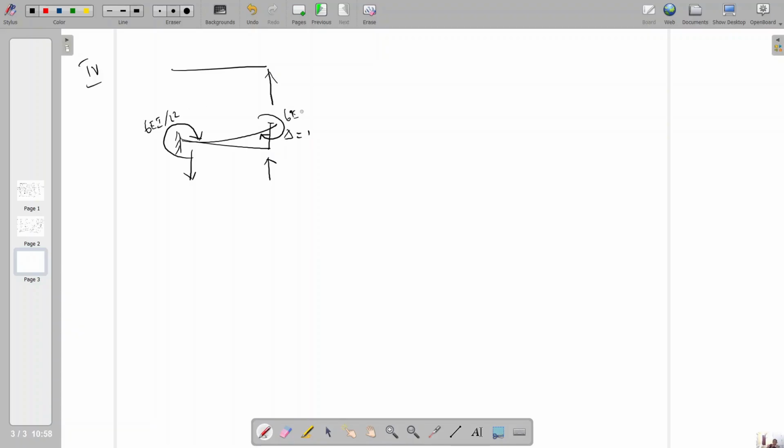So we already know that the moment due to the support sinking is 6EI by L square. Here also 6EI by L square, and the reaction due to this moment, summation of moment by span, is equal to the reaction VA, which is 6EI by L square plus 6EI by L square, as in the case of the previous subdivision. VA is equal to 12EI by L cube, and VA is equal to minus VB, same 12EI by L cube.